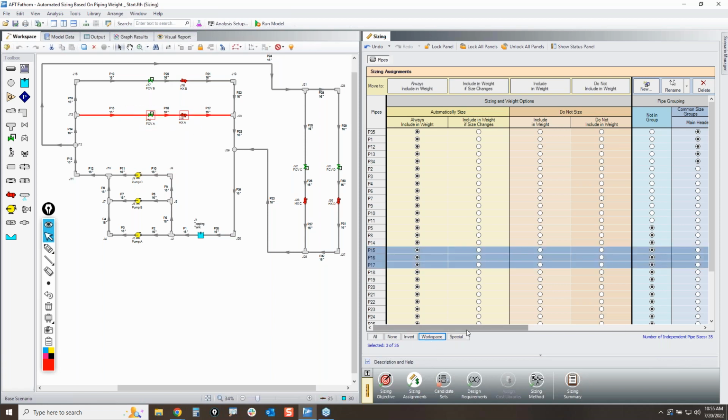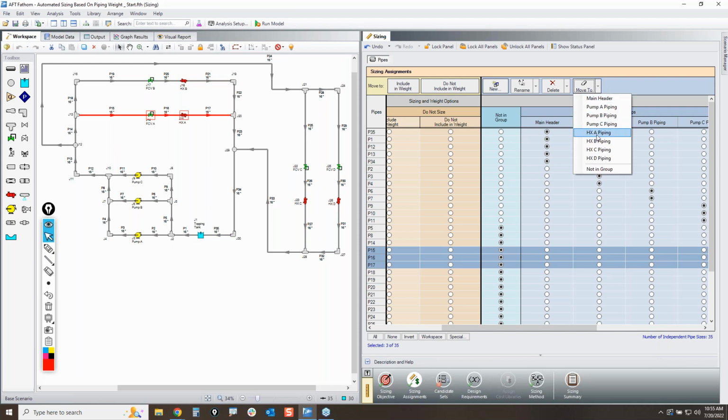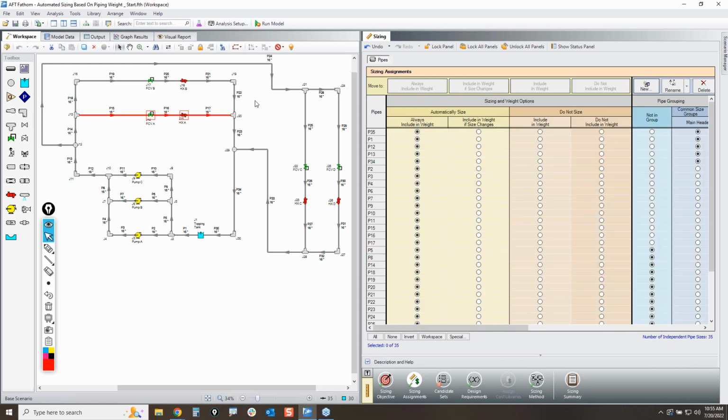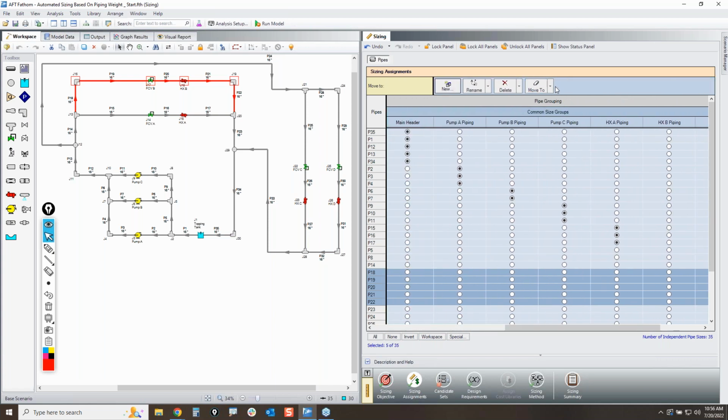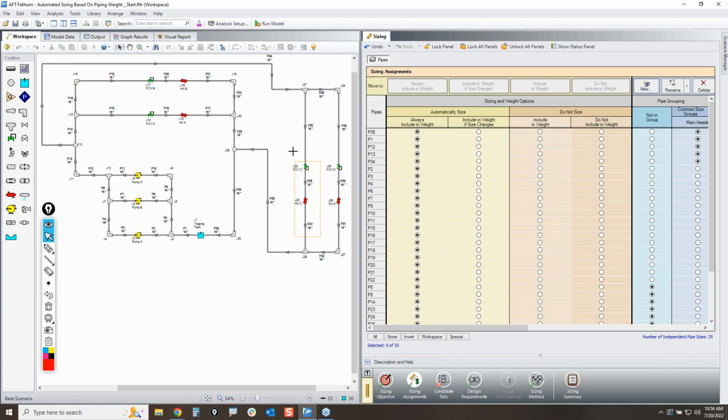So this is heat exchanger A. This is actually more pronounced because here we will see that we'll have different pipe diameters for the two different paths here for the parallel heat exchangers. They're operating in parallel. So that is a situation where, if the hydraulics were exactly identical, then you might end up with the same sizing, but not always.